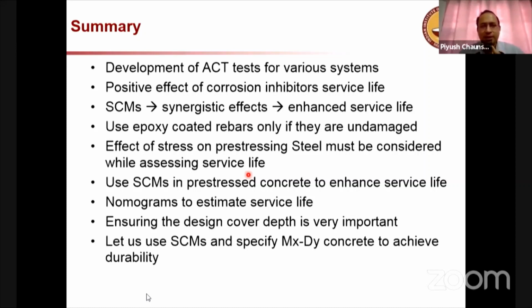I will start with, can you comment on a size effect for the chloride threshold value and its scatter going from mortar to lab concrete to full scale specimens? Definitely, there is also literature on this size effect, and that's one of the reasons why we moved from my first test specimens, which had about 1 centimeter long exposed region. Now we are using about 5 centimeter long exposed region.